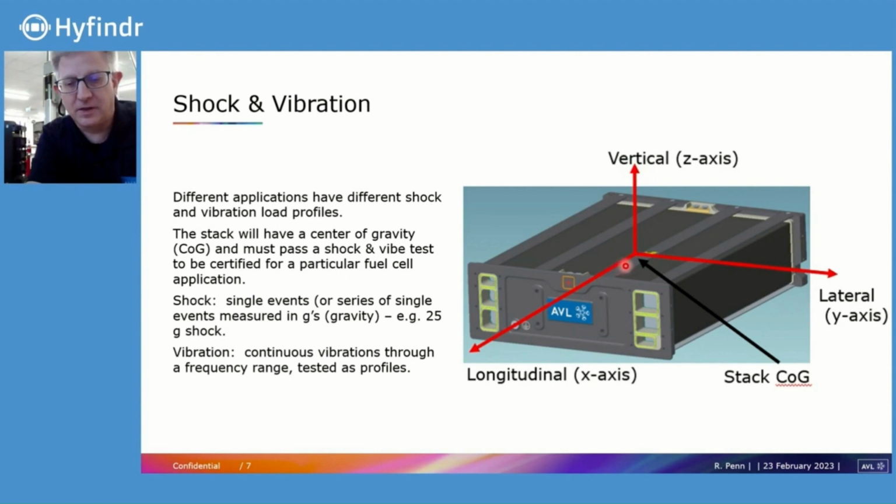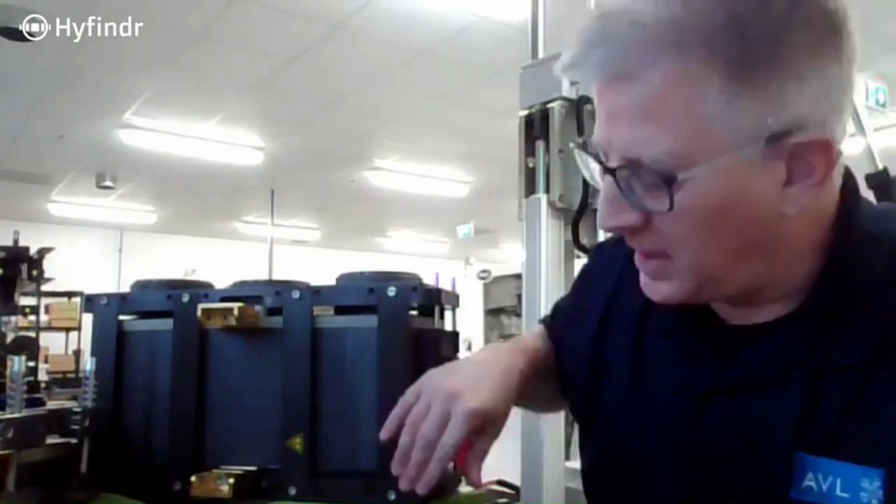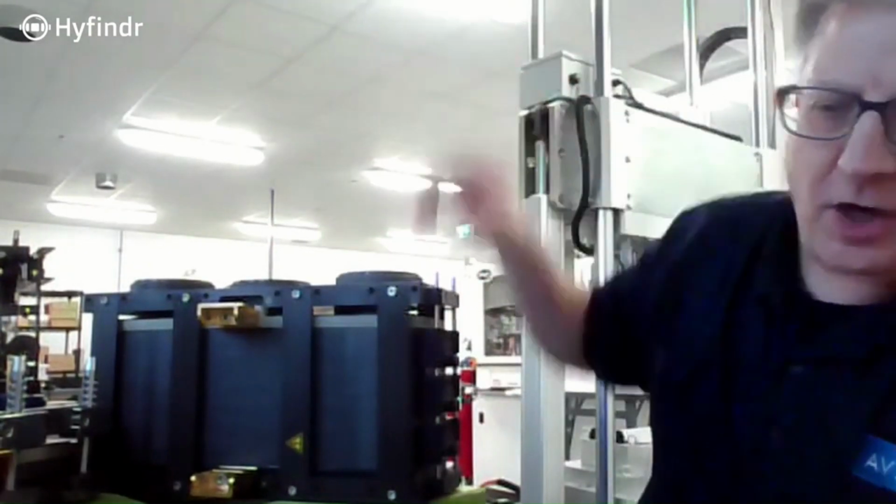And how that affects the number of cells is that when we stack them one against another, these cells all have gas diffusion layers, which are made of carbon fiber paper and are compliant, as well as seals that are meant to compress under the stack load. And as you stack up more and more of these cells, it becomes very squishy and less solid. Well, the one next to me is under compression and is very solid. But if you think about extending this higher, higher, and higher, you end up with this deck of cards.